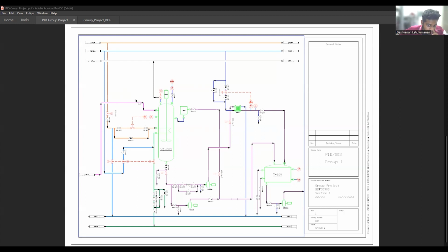CPO during polishing, and also the CPO bypass, using a feedback control system for the temperature control valve, and the cooling water from the cooling tower interconnected with the condensate line, and also the condensate line bypass and the drain. So we have another additional equipment here, which is the heat exchanger.